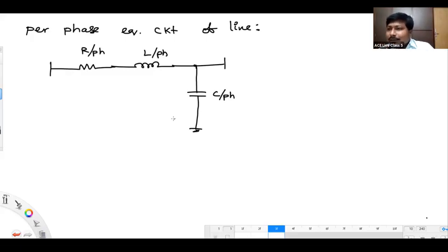Now the thing is, generally if the conductors are carrying some current, definitely there is some heat generation, heat production in the conductors. That heat we are going to represent in the form of a resistor in the electrical equivalent circuit. Don't write, just listen. I will write these things while I am going for the separate discussions. So what is that resistor representing now? Simply, it's going to represent the heat generation in the power conductor during the current flow.